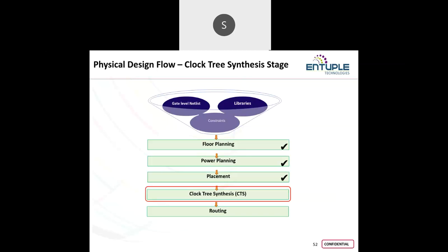Approximately, what expectations are you getting? Usually, for power optimization, in the placement stage I'm adding the standard cells, and the power distribution I'm doing might be based on the standard cells. So whatever report I check in synthesis, and after the synthesis in the physical design stage, I am adding some standard cells into the design and checking the power report.